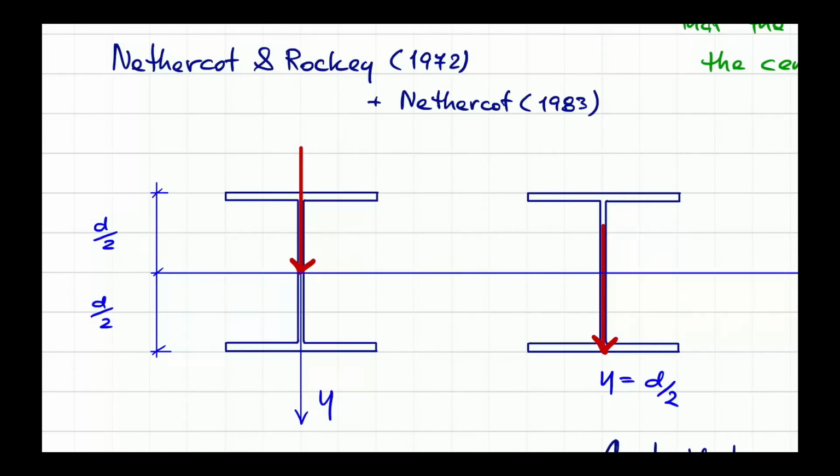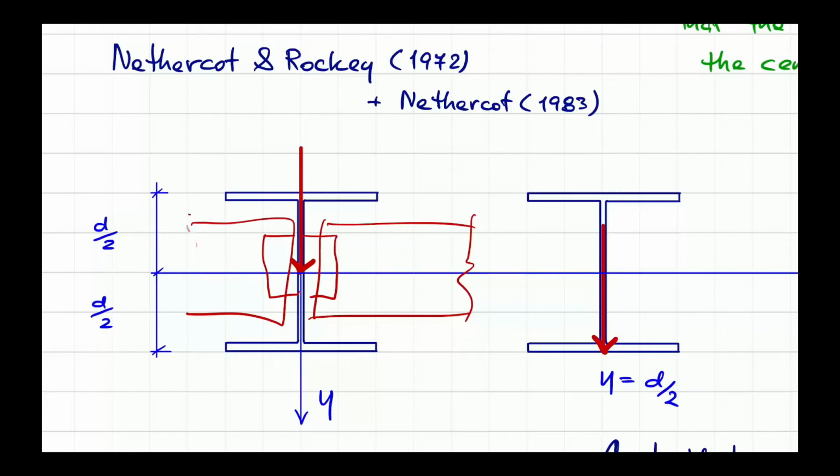Generally, when you construct the steel frame using the wide flange cross section, you have the beam. How do you put the load? You put the load at the centroid? Well, in some cases, it might be. For example, if you have the plate welded to your web, and then this plate transfers the load from maybe the sub beam. Yeah? So you have the load acting right at the centroid. Okay, that is possible.